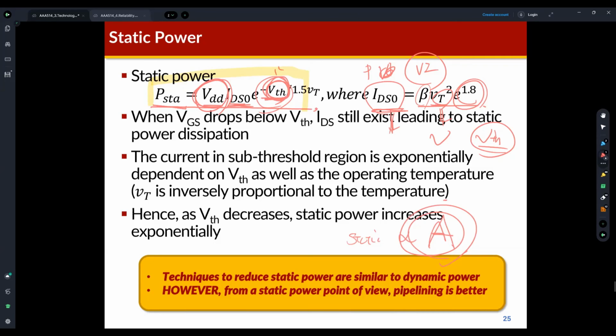So if we just consider the static power, multi-core is not a good idea. With multi-core we can increase the performance and throughput of a processor, but if we apply the multi-core architecture, then the area is also increased, which means the static power consumption also increases. That's the problem.